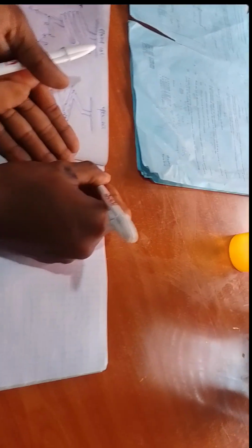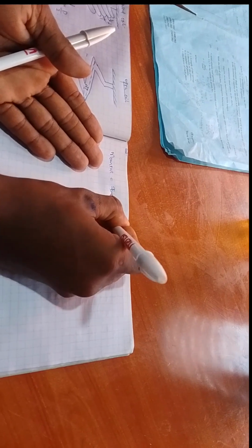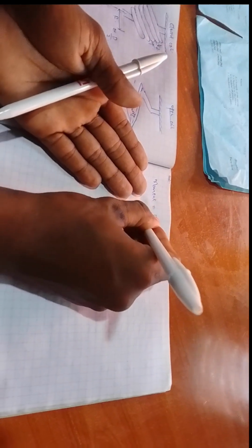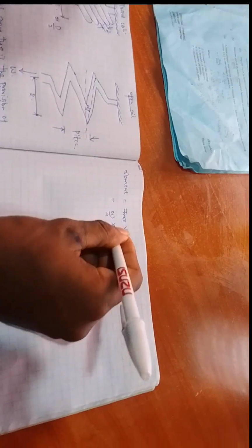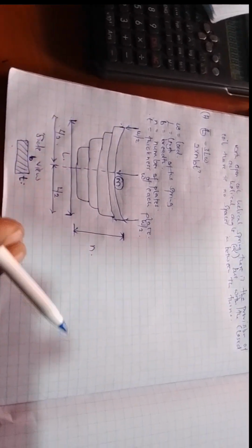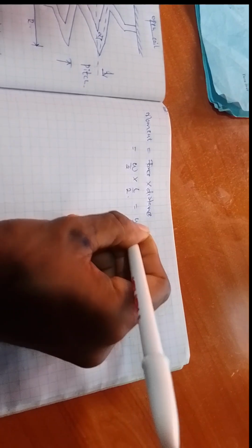And we know from module 1 that moment is equal to force times distance. The force acting from one edge of the section is W over 2, times the length from this side to this side. The clockwise moment and the anti-clockwise moment acting, particularly here, is W over 2 times L divided by 2. So the total moment is WL divided by 4.